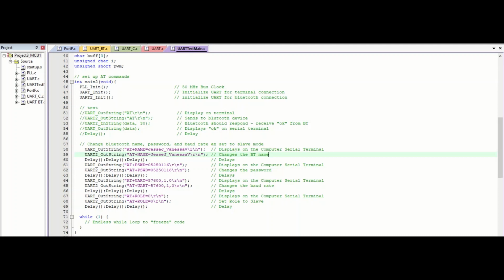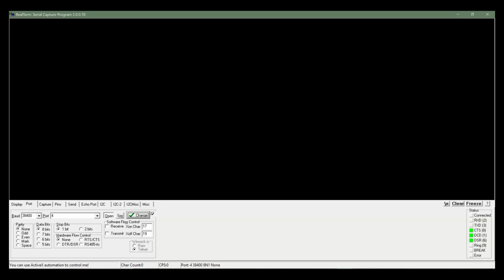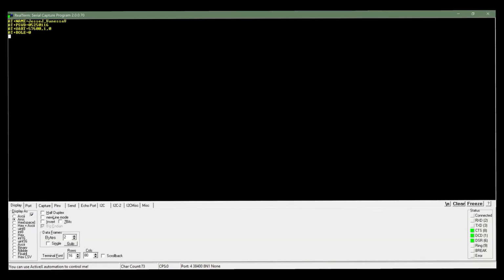The goal of this project was to initialize and set up UARTs and a Bluetooth module to allow for communication between a phone's serial terminal and two TIVA boards. We begin by configuring the board to the specified parameters. This is accomplished by sending a string of AT commands to the Bluetooth module while it is in command mode. The preceding video demonstrates that the module was configured.